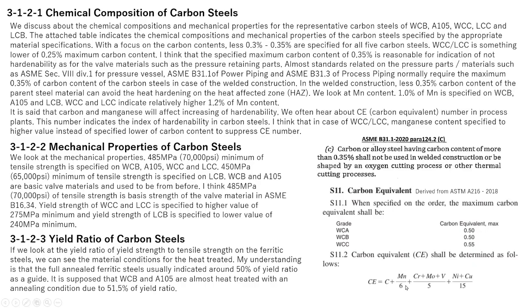The other elements, chromium, molybdenum, vanadium, nickel, and copper, are also hardenability elements, but not so effective. So sometimes we consider the carbon content and the manganese content.